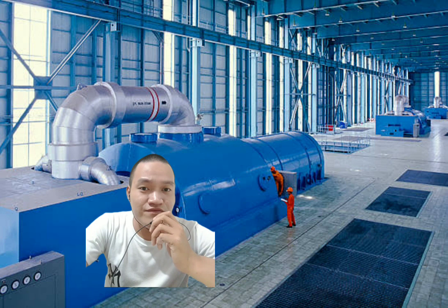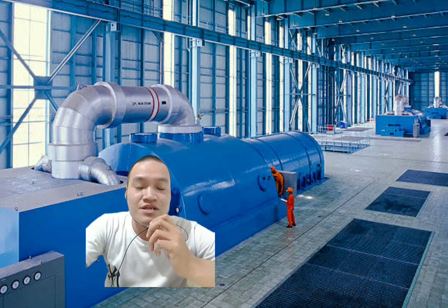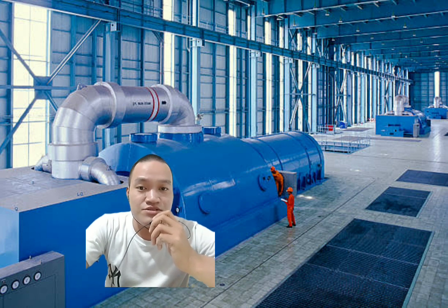While waiting for the first movement from the bridge, and between movements, the turbine must be turned ahead once every 5 minutes by the use of a steam blast. If there is any delay, the gland steam and vacuum should be reduced.